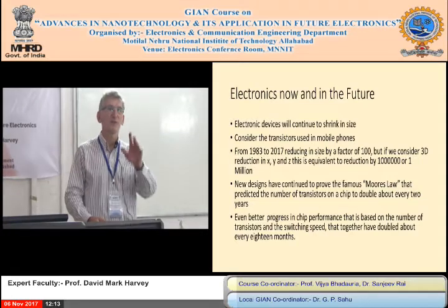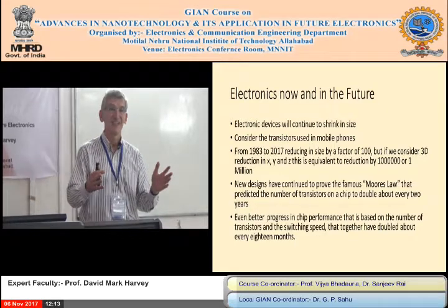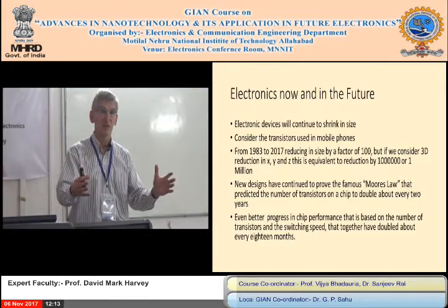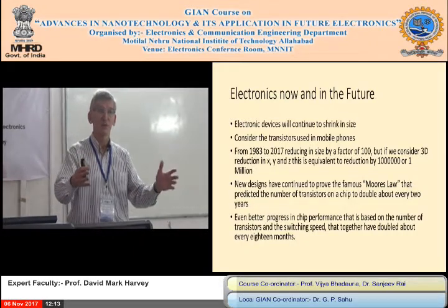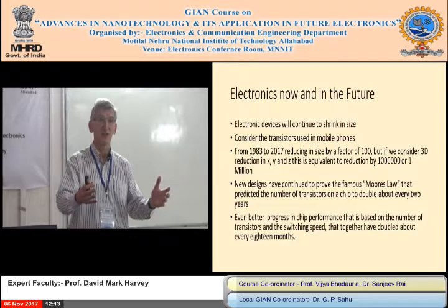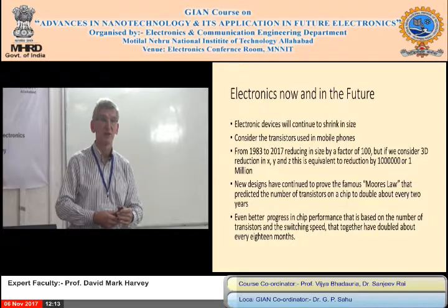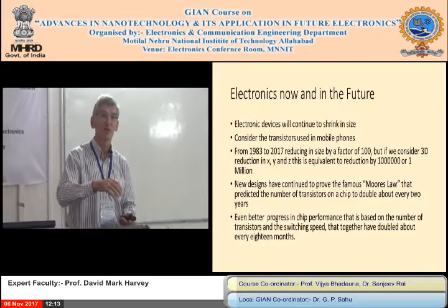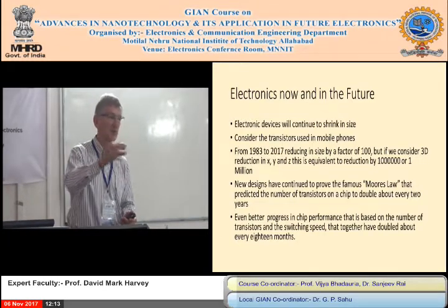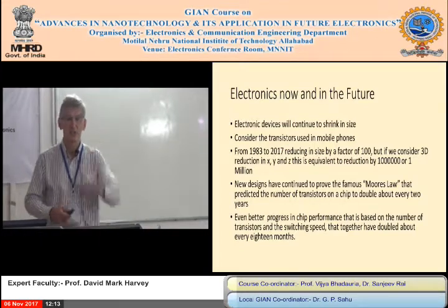I'm going to talk about it on Thursday or Friday, but briefly, the testing device for heat is like a big pizza oven. It's a heating and cooling chamber, and for vibration it's like a big piston that vibrates. We call it a shaking machine. So big mechanical devices for shaking, like a big motor you could say, and a cooling and heating oven, a refrigerator and oven combined. For humidity you have a spray system. Actually spraying water, and maybe salt water, because you get salt on the roads in colder countries for ice. They actually have salt spray. Anyway, I'm going into that a bit more on Friday, but I can discuss it later.